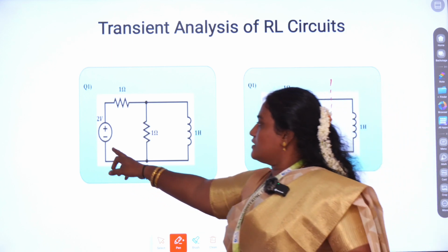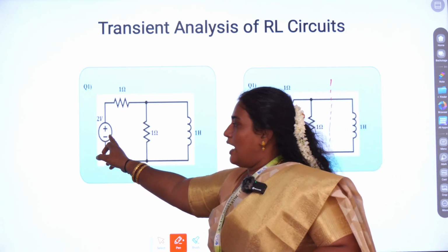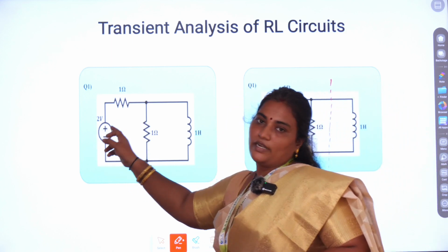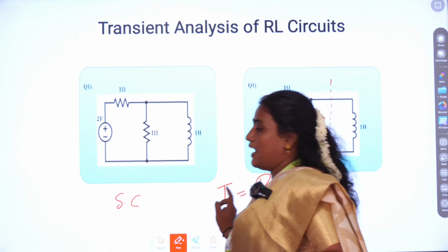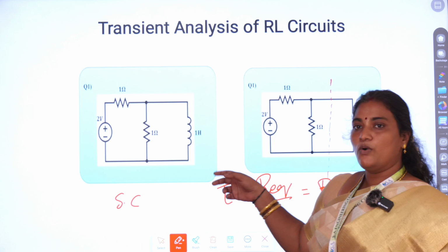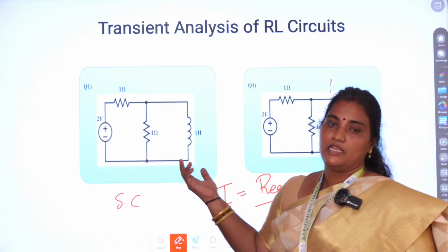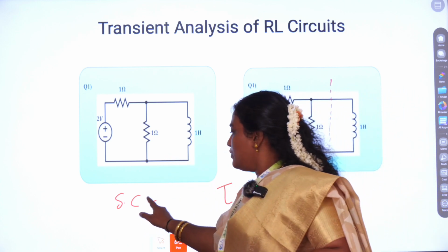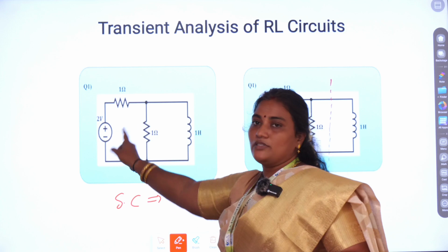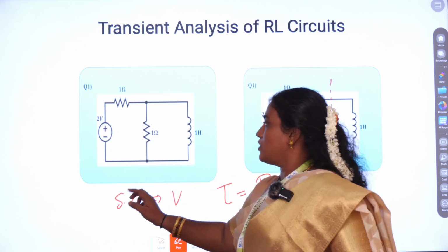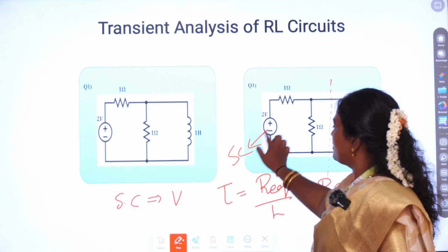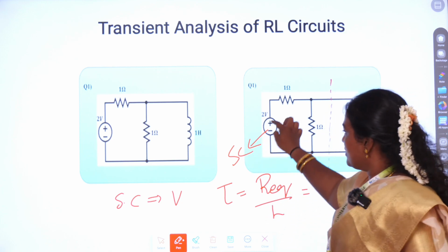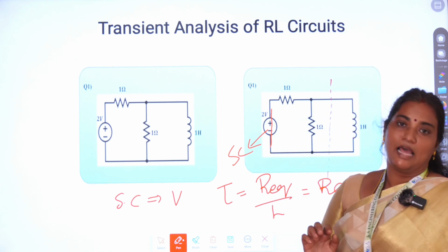So here, first I have to short the voltage source. As we all know, when you want to find an R equivalent, as you would have done with Thevenin's theorem and so on, we short circuit the voltage source. So the voltage source is short circuited. When I short circuit this voltage source, it will not be available, so it will be a line.